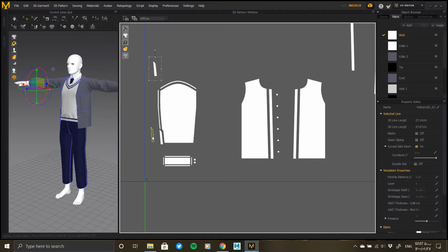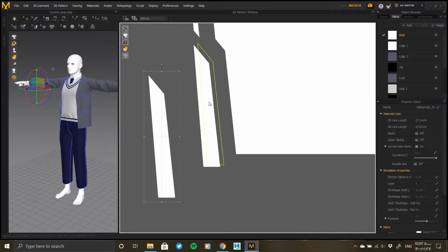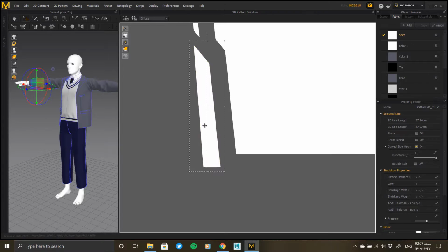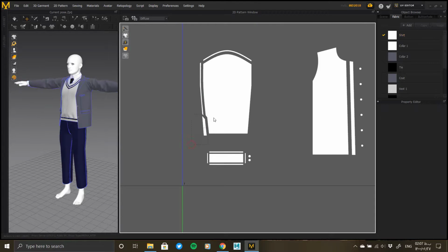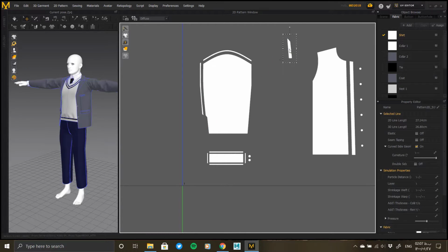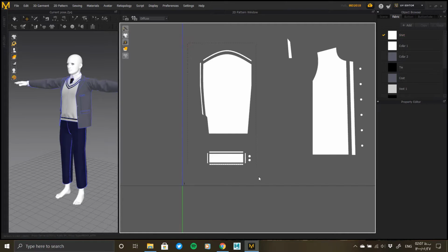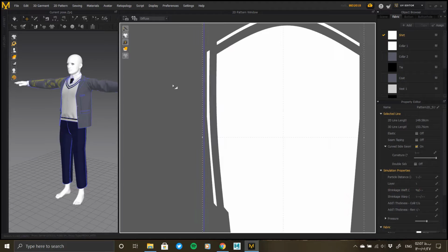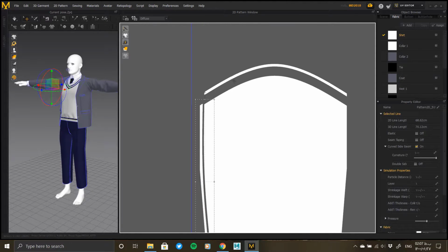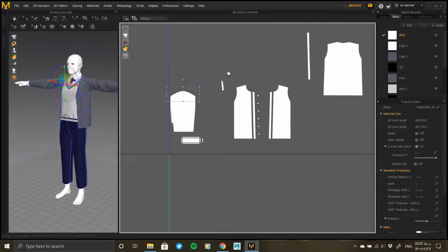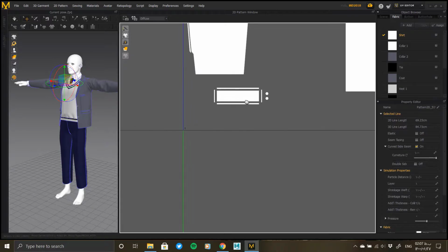You can set the unwrap type based on UDIM, and set the whole clusters on 2 or more UV screens. In this case, each of the clusters will be placed in a larger size, and the texture will be placed on it with higher quality. The larger the clusters, the more UV space they take up, and the higher the quality of the material. Try to adjust the clusters so that they are as large as possible in UV.